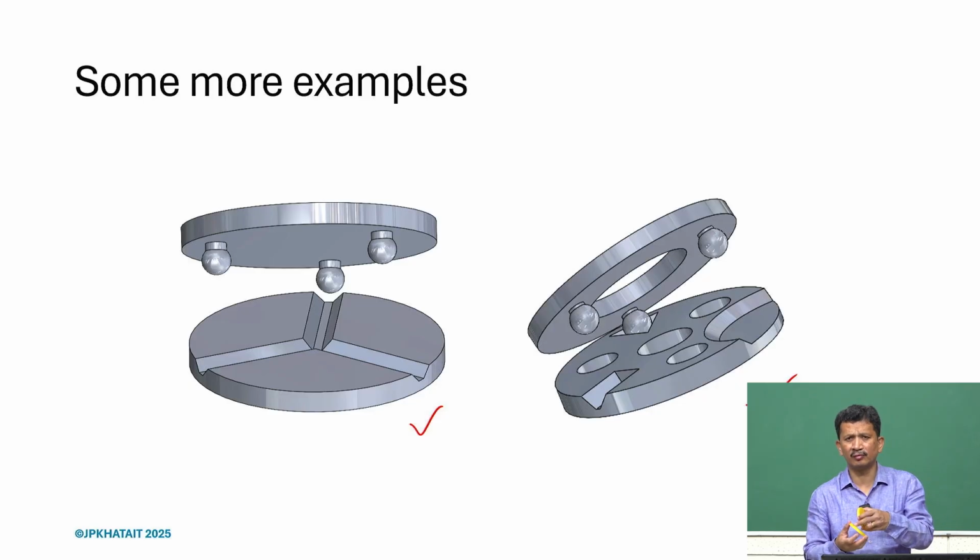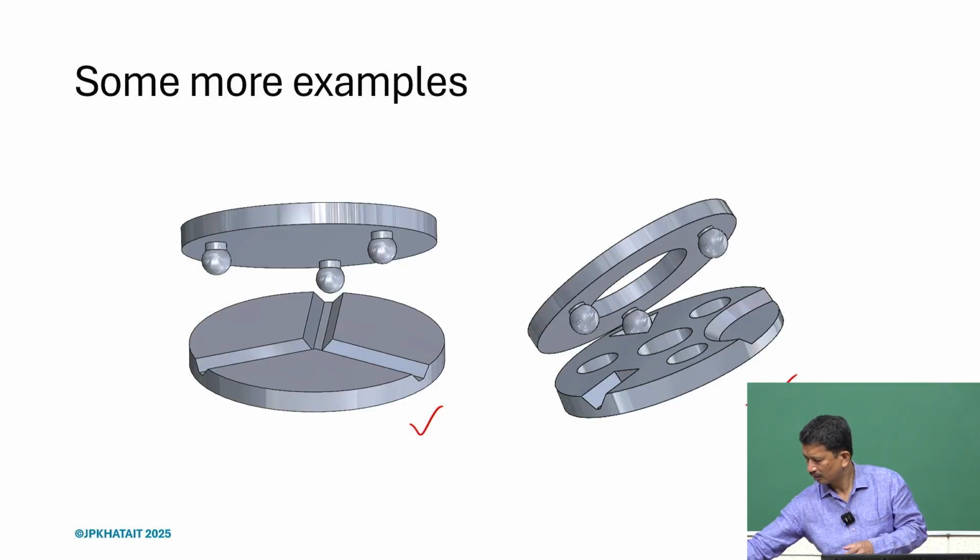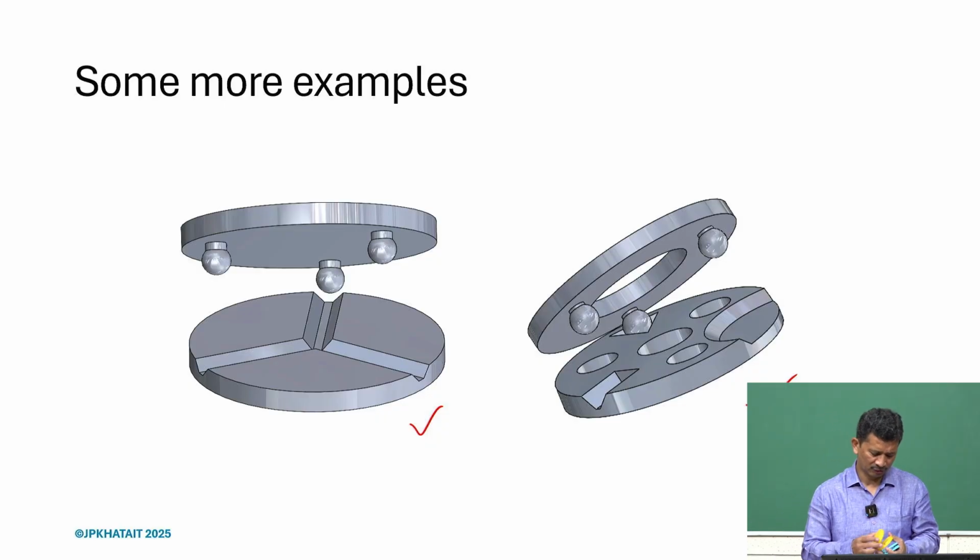These features can be embedded in the design, even hidden somewhere, and the moment we put it together, we can see it goes to the same location all the time. Yes, there are some issues that we can discuss, but these are the principles, and that's how we can start. These are very old designs, mainly used in optics. It's called a kinematic clamp, or even a Kelvin clamp. Here you see 3 times 2, so a total of 6 contacts.